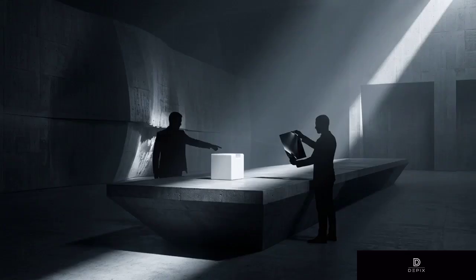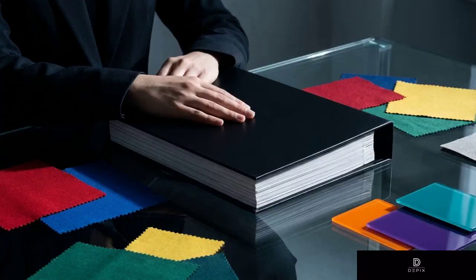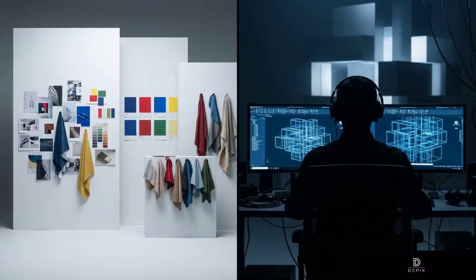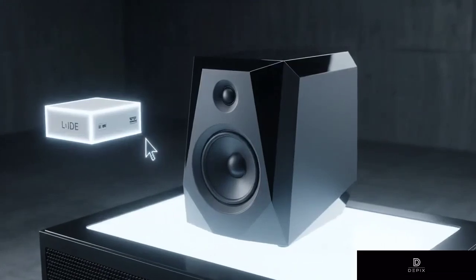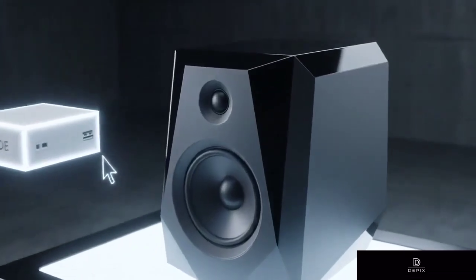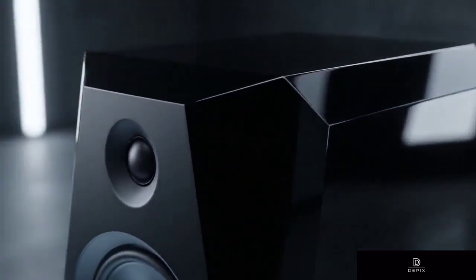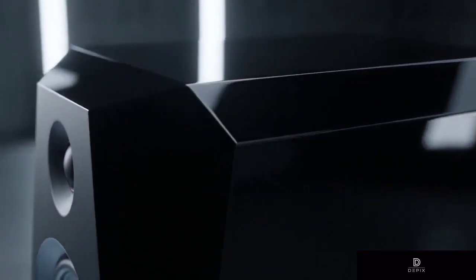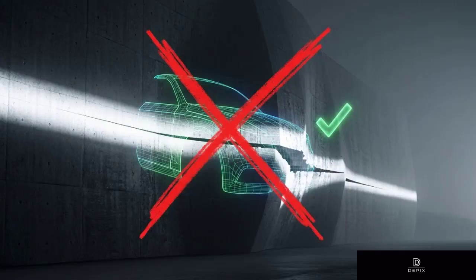The pipeline conflict happens because the decision to make a product gloss black is often made late in the development cycle. That call comes from the color and materials team, who operate completely isolated from the engineers building the geometry. The brief says gloss black, and that late decision retroactively forces an expensive G2 mathematical standard onto a 3D model that the geometry team originally built and approved at a simpler G1 standard.